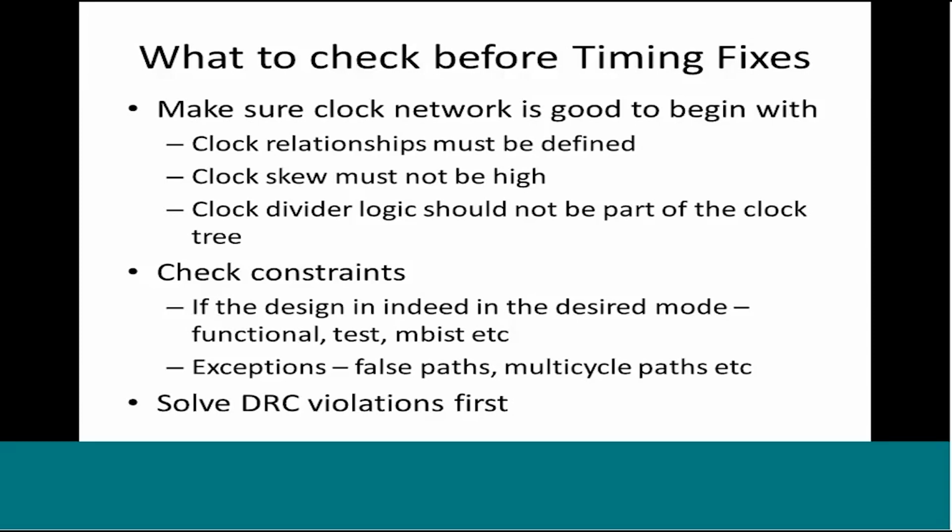Each company in the industry will have its own set of scripts or its own set of tools, maybe internal, maybe external. Maybe they will purchase a tool from a vendor. So they will have a set of tools which will generate timing ECOs based on the PrimeTime and the STA tool results. And these timing ECOs will be applied again in backend, and a new version of the database will be prepared for timing analysis. So this is an iterative analysis.